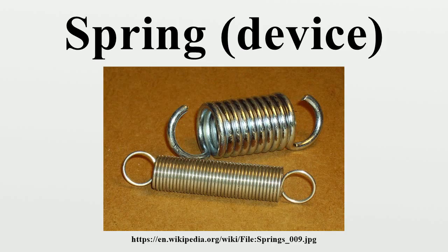Zero-length springs are made by manufacturing a coil spring with built-in tension, so if it could contract further, the equilibrium point of the spring, the point at which its restoring force is zero, occurs at a length of zero. In practice, zero-length springs are made by combining a negative-length spring made with even more tension, so its equilibrium point would be at a negative length, with a piece of inelastic material of the proper length, so the zero force point would occur at zero length.